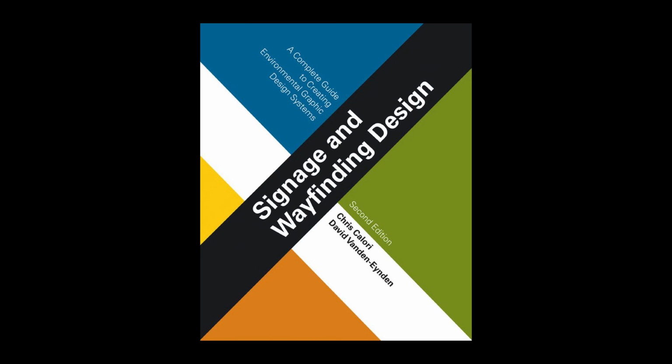LED matrix modules can be seamlessly assembled into very large screens of more or less customary proportions. Think rock concert or sporting event screens, or into horizontal linear ribbons. Think Times Square zippers. The resolution of conventional LED matrices tends to be fairly coarse, but it's constantly improving. The rather large depth of conventional LED modules can be a design consideration. See figures 6.56 through